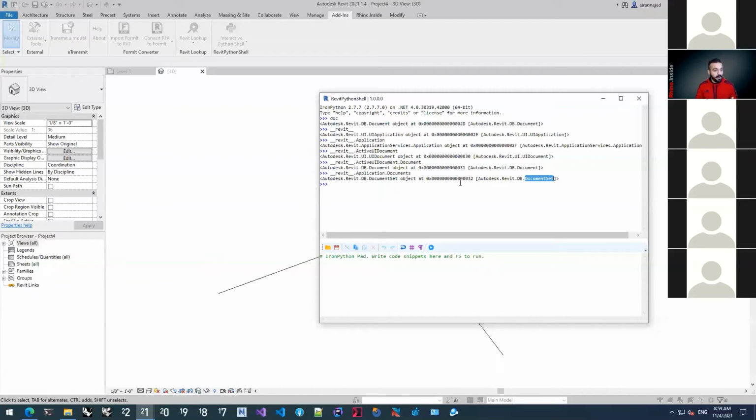And in order for Revit to be able to actually load those contents inside the host model, it needs to load all those documents, right? So if you have one Revit document open and it has 3 other models linked in, you actually have 4 documents open at a time. One of them has a UI document attached to it because it's open in the UI and you can see it. The other ones don't have a UI document. They're only open in memory.